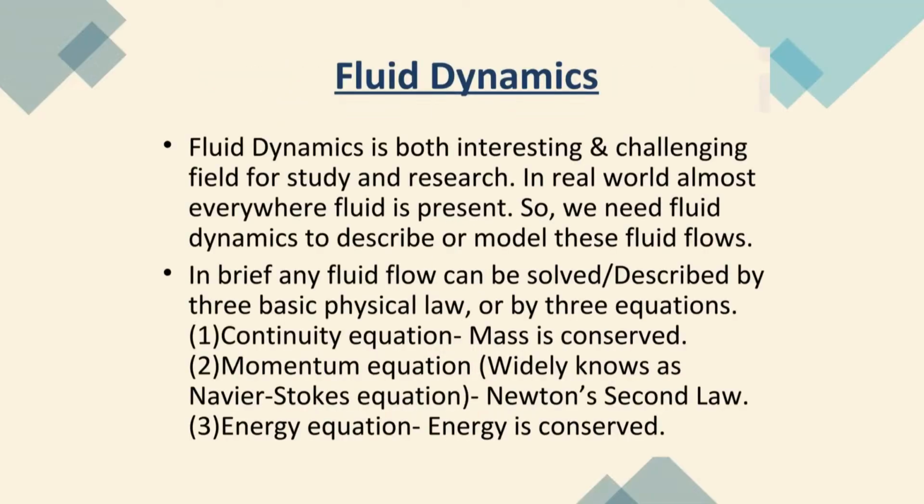Okay, so, you know what fluid mechanics or fluid dynamics is. But here we want to see, in brief, that fluid flow can be described by three basic physical laws. There are more if we include other things like particles, but this is mainly the fluid flow. That is the continuity equation, where mass is conserved, which we already discussed this morning, and the momentum equation, known as the Navier-Stokes equation. That is based on Newton's second law of motion, and the third one is the energy equation, if you want to solve any temperature or energy field. So, mostly we will be dealing with these three equations using Ansys.